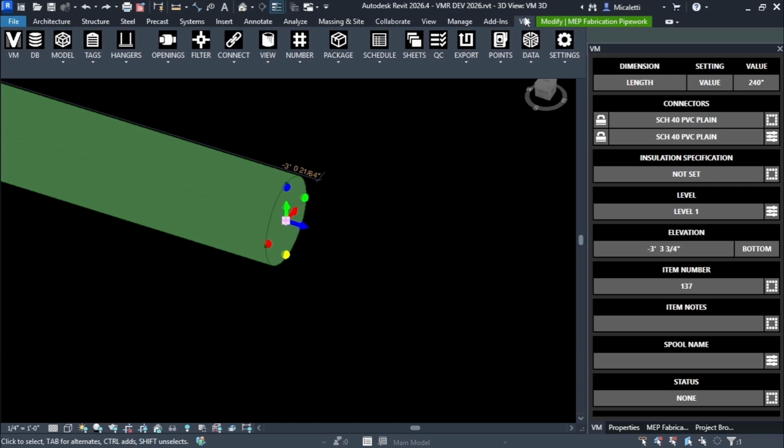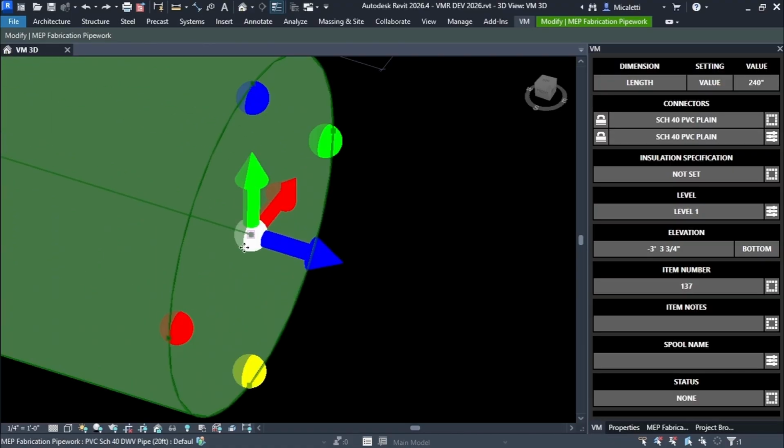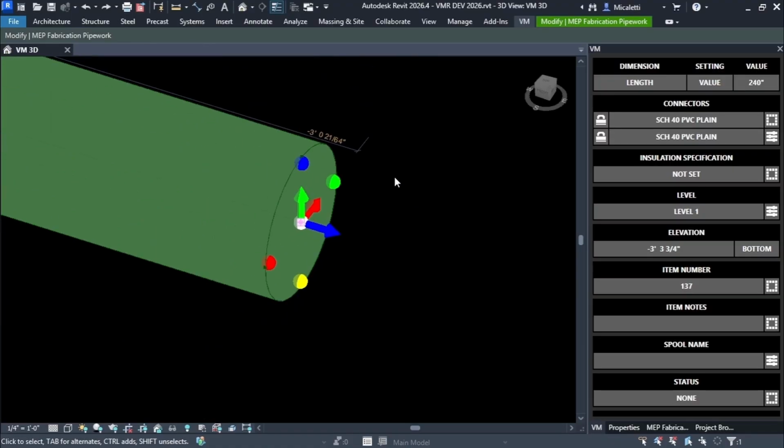They hide a lot of the stuff they're doing, pretending they're adding features when they're just built into Revit already, in a lot of ways. Now, I'm not saying that this is true here. I don't know what they're doing with this point manager, but point manager is basically a schedule, and if you're familiar with Revit schedules, they're very powerful. These are just parameters. This blue point is a parameter, green point's a parameter, yellow point's a parameter, red, and so is the white. And not only that, they're on this pipe.